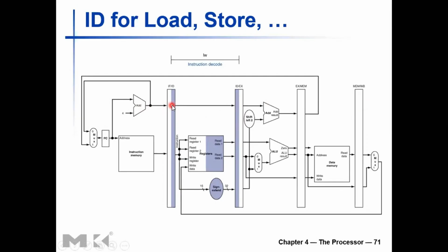Okay, right. Back to the details. So at the start of the clock cycle, your pipeline register gets updated with the instruction word and PC plus 4 value. That will consume some time. And a reading delay will be consumed to propagate that value to the rest of the hardware, right? So the writing and reading latencies of the pipeline register are consumed at the beginning of the clock cycle. Then what will happen?